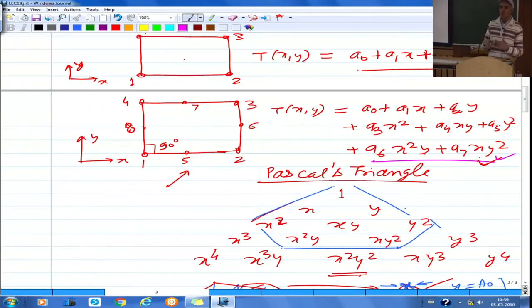So this will give you, along a common boundary which is an inclined boundary that is not parallel to either x or y coordinates, a temperature variation that is going to be cubic. And you have only, say for example, 3 common nodes, whereas the variation is involving cubics, that means 4 terms essentially. So again you won't be able to get a unique temperature variation from this side and from the other adjacent element if the edge is not parallel to x or y.